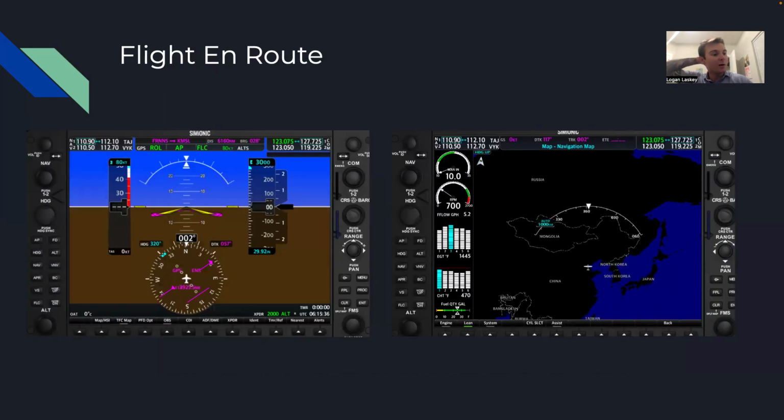I've taken off out of Walker County and I'm now in controlled airspace. I will pick up whatever directions ATC provides me. And this is when we're going to get into a little bit more of the programming of the system. So, what I have loaded in is I have an autopilot. And what I'll do is when I take off and I get close to that 1200, I'll go ahead and hit heading FLC, heading FLC, nose up or nose down to get me to that 80 knots.